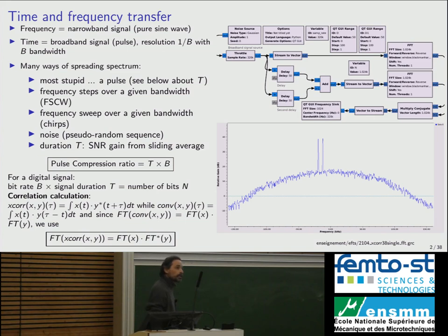We're used to having frequency as the inverse of time, but when you're disseminating time and frequency, there are actually two orthogonal quantities, and there is actually no relation between accuracy in time transfer or frequency transfer. If you think of it, frequency is a narrowband quantity, meaning that you just consider a sine wave. What is characteristic of a frequency transfer is a pure sine wave, which has no time characterization. Every period of your sine wave will look similar to the neighbor. So you have no timing capability in terms of time transfer, in terms of frequency transfer.